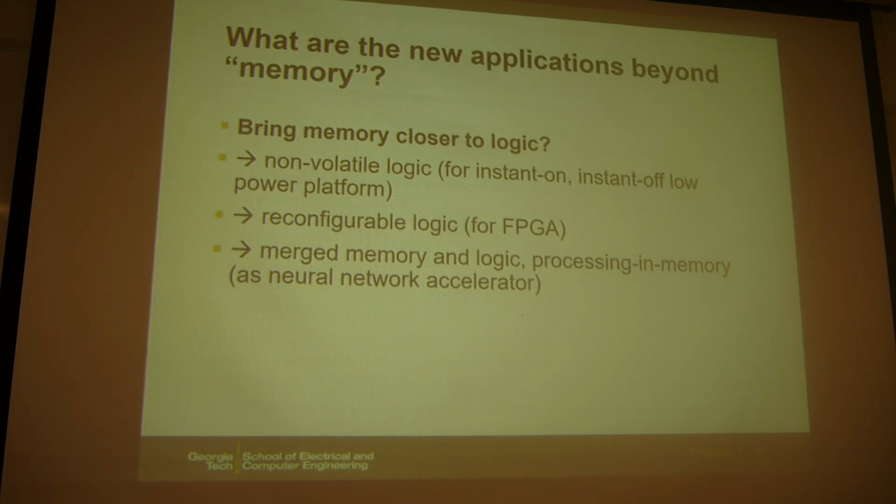So the idea here is to store your logic state to the non-volatile memory on chip. So then you can power off your chip and save the energy during the standby mode. And then you can later turn on your chip, and then you can resume your logic operation right away. So this is one of the applications, and we call this non-volatile logic.